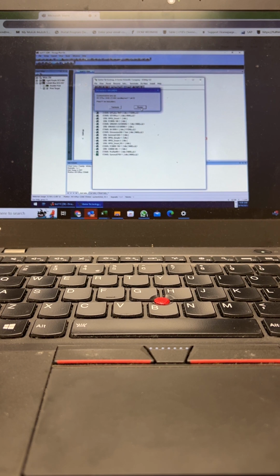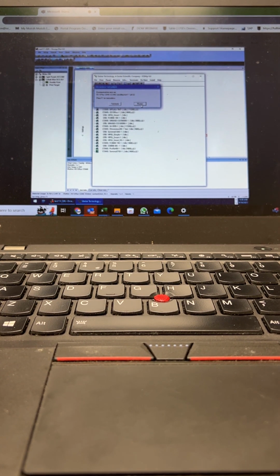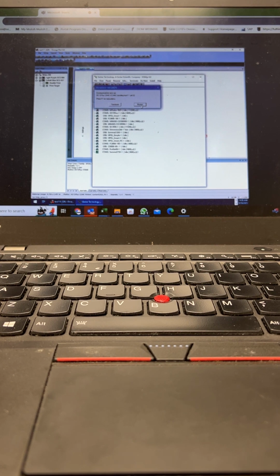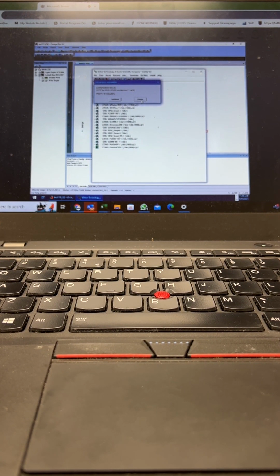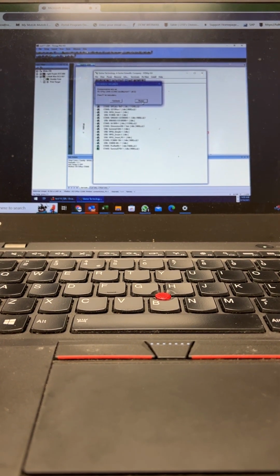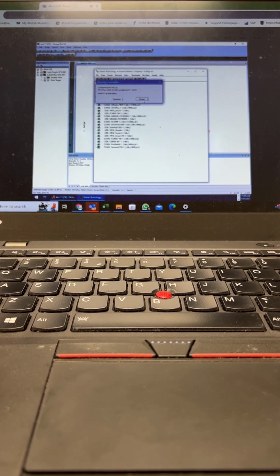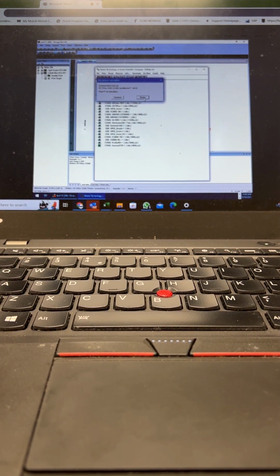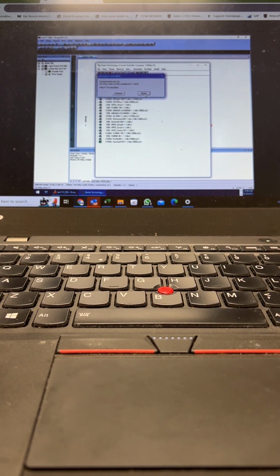So first thing I would check, make sure your plotter is physically turned on and that you have the USB cable connected to your computer and the serial cable connected to that, then connected to the plotter. Common mistake is you connect the USB to serial adapter, you forget to plug in the serial cable going to the actual plotter. Thus it says I can't communicate, or it just sends it, but nothing shows up on the plotter. So always double check that you actually have all the cables connected to the device. Sounds simple, but with all the other stuff you got going on in an install, it's a common one to forget to do.